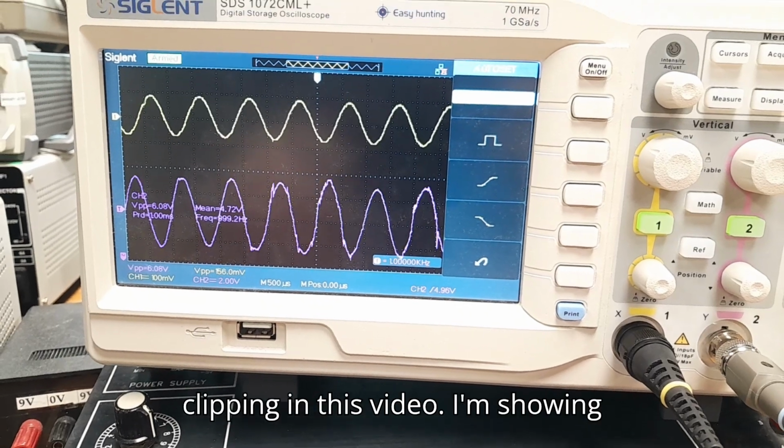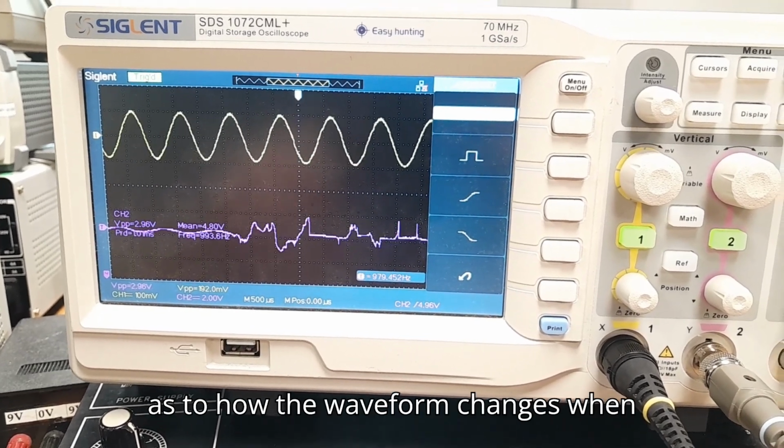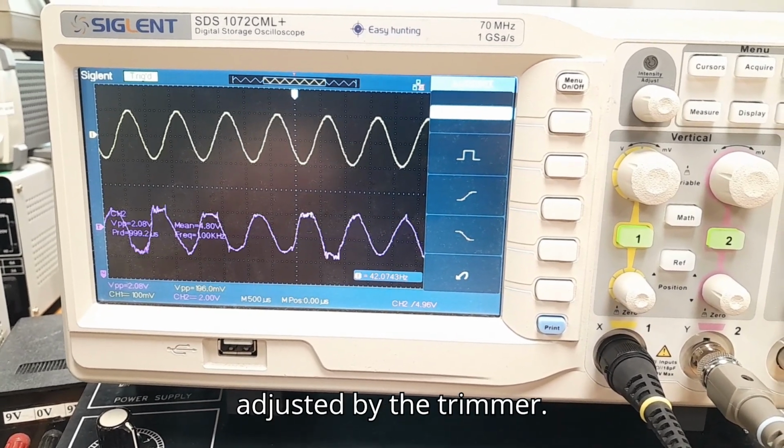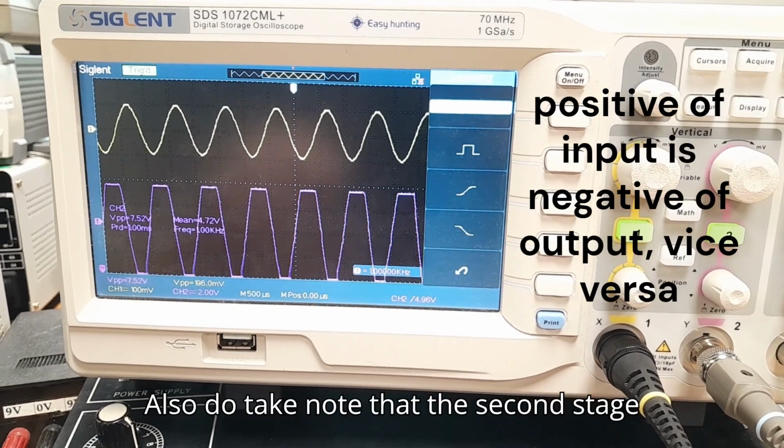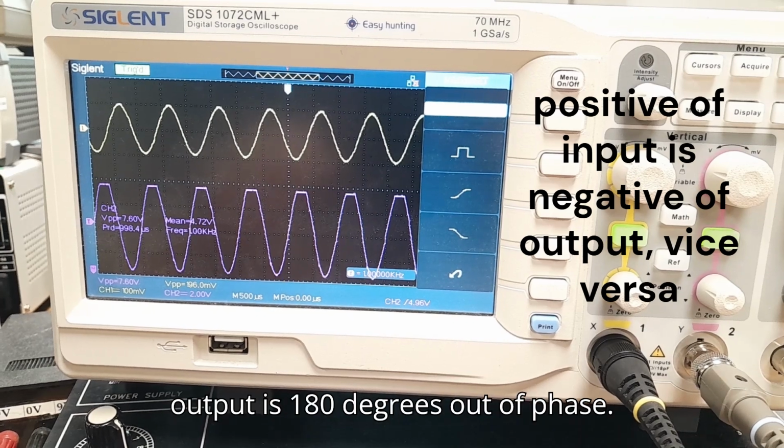In this video, I'm showing just the oscilloscope for a clearer view as to how the waveform changes when adjusted by the trimmer. Also, do take note that the second stage is an inverting amplifier, hence the output is 180 degrees out of phase.